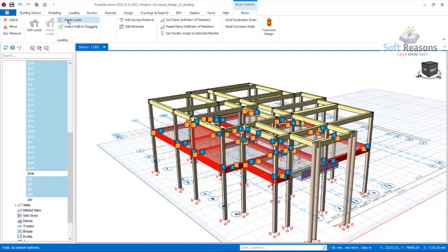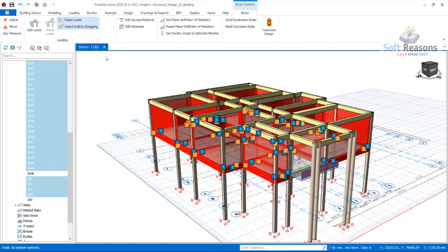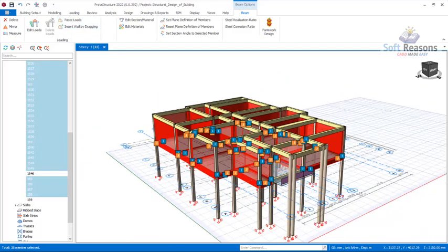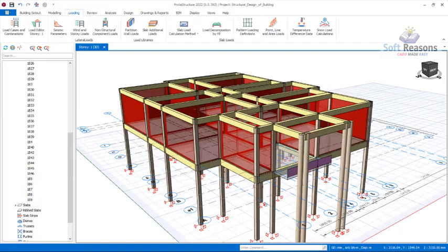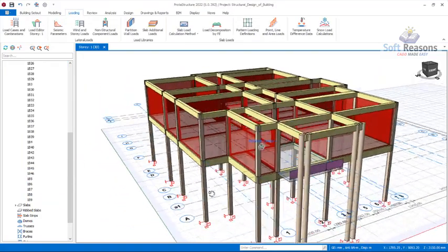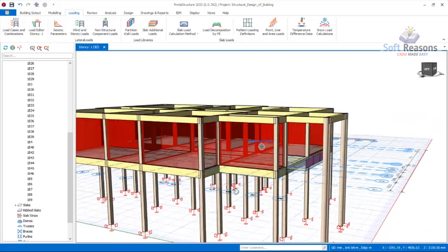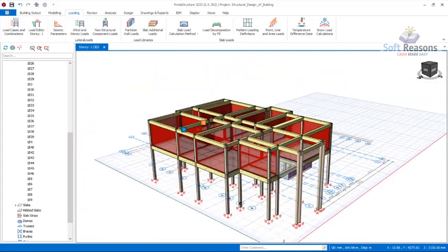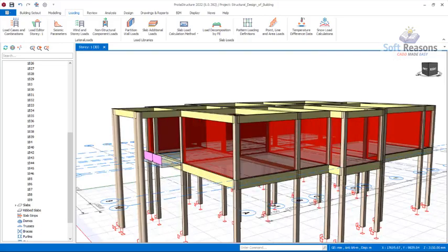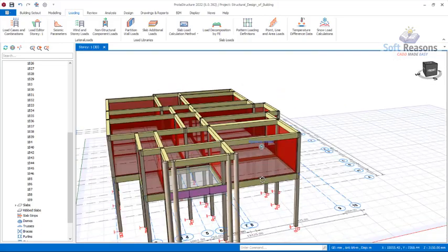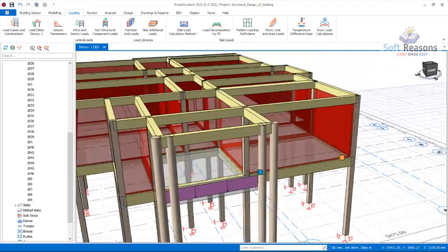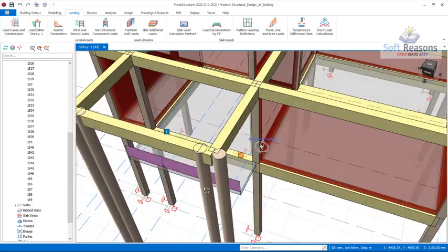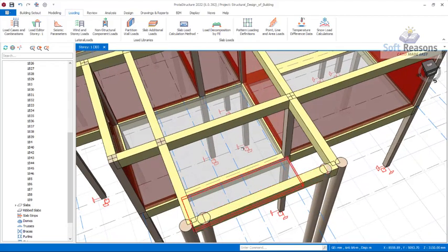You can see options of paste loads right there. Click right there to paste the load successfully, just like this. So if you check very well, you can now see we have loaded all of the reinforced concrete beams with the wall loads successfully, just like this. Okay, so having loaded these beams, there is a load along here because there's a wall running along here, along this foyer's provisions, this place.